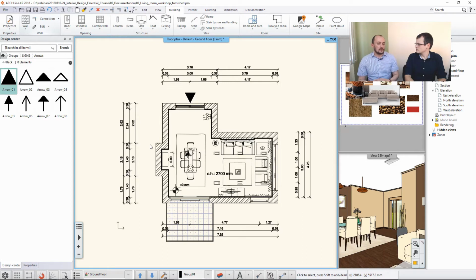And then you will be able to control what you will see, not just on the rendering as we covered before, but also when you would like to create something like what I will do now. I will create 2 separate versions of the same drawing. This is what you can use for that. By turning on and off certain layers, you can customize what you want to show.